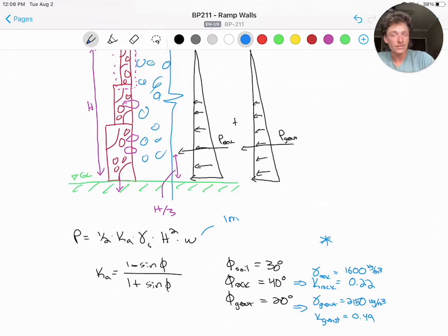The calculations and diagram I'll show you below will go through an example calculation for the worst case scenario, which occurs along a 30 centimeter wall, where we'll assume zero tensile capacity at the connection between the section of wall and the wall below. And we'll also distribute the load by volume.